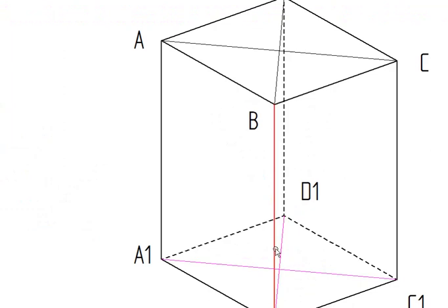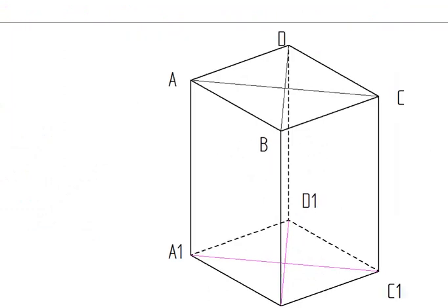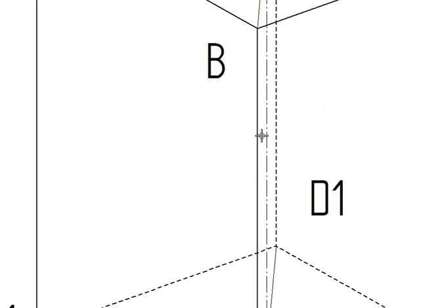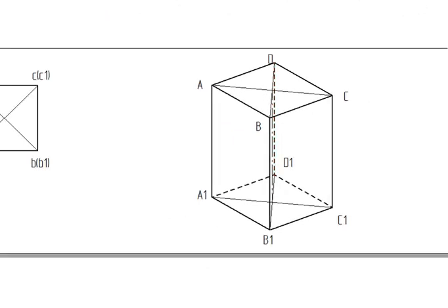Now I am going to consider an axis line, which is going to be the center of this square prism. This axis line should be a thin, dashed line. The line should be like this. It is an axis line: a long dash, space, small dash, again space and long dash. This line should be a thin line.